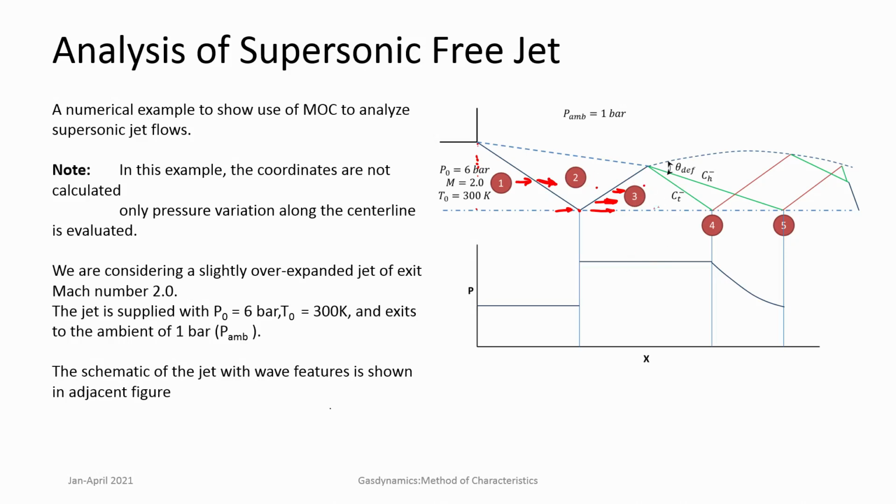So, if you look at the centerline pressure variation, initially you have a pressure which is lower than ambient pressure, and then suddenly the pressure will increase higher than ambient pressure. In region 2, it will be exactly ambient pressure. This is a case where we are looking at a reflection of waves from a free pressure boundary, and we know to achieve that the pressure at the boundary should always be 1, and we find that pressure at 3 is higher. As a consequence, it develops expansion fans, and then further you can see how pressure varies. Here flow is non-uniform and pressure varies in a smooth manner.